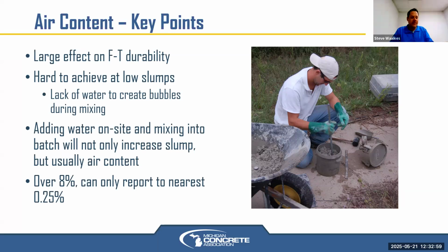All right. We don't have enough time to really address that, but yes, I kind of alluded to it earlier as far as unhydrated cement particles, if you don't have enough water on the surface, as well as potentially too much water on the surface. Yeah, those are the main reasons why we have scaling, and we generally see lack of curing as the main cause of scaling. All right. We're caught up on questions.